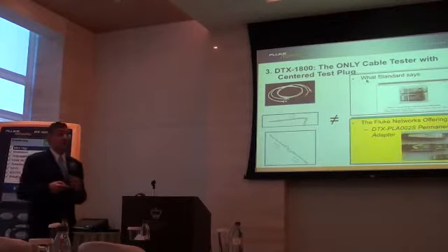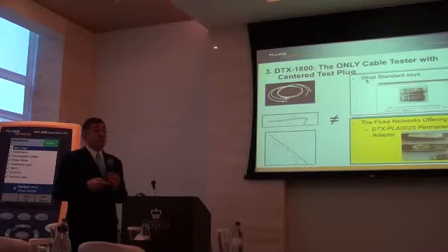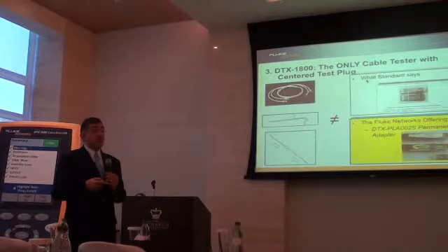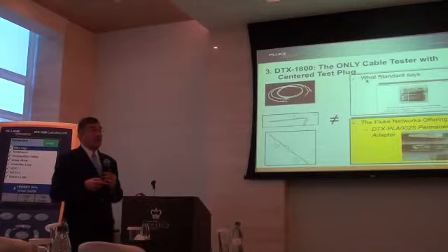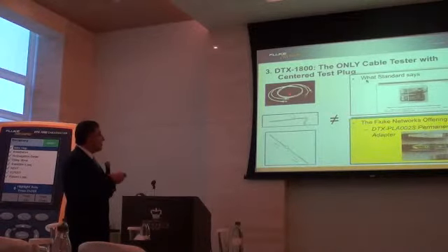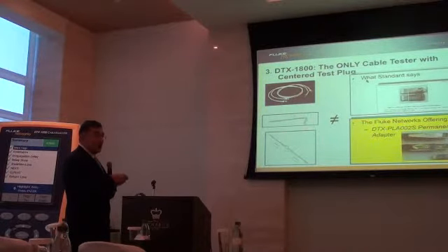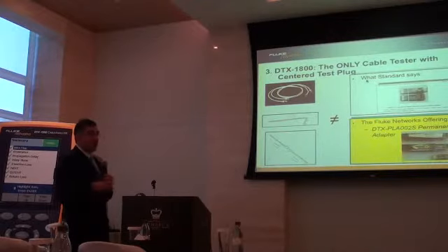Can't you do like in the fiber optic when we do the patch cords, you just subtract the patch cord, and then you test the link? So in the same way, whether the patch cord is very good or not, if you know the amount of the loss in that one, your meter, with built-in electronics, you can always subtract that. Can't you do that? No, you cannot do it, because once you take a patch cord and you untwist and twist, you will get crosstalk issues. It's true, like I'm saying in the fiber. Exactly, but the problem is that the result that you want to subtract is not repeatable.